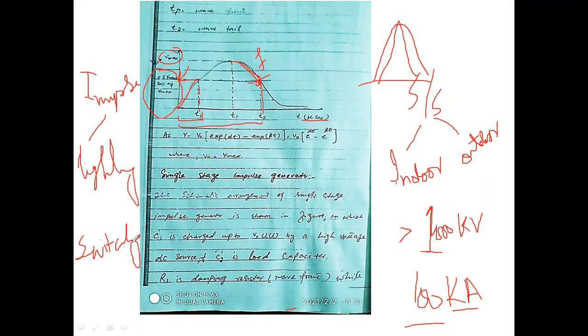Their amplitudes are always related to the operating voltage, and the shape is influenced by the impedances of the system as well as by the switching condition. The rate of voltage rise is usually slower, but it is well known that the wave shape can also be very dangerous to different insulation systems, especially to atmospheric air insulation in transmission systems with voltage levels higher than 245 kV. So when the voltage is greater than 245 kV, there is a high chance of switching overvoltages, which appear in the form of impulse.